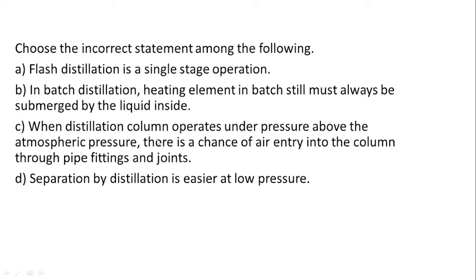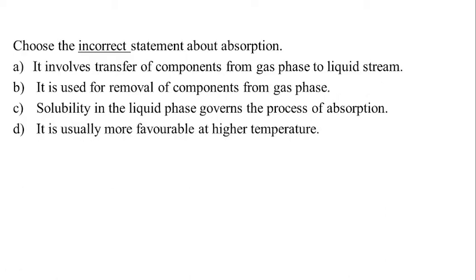It's like this. In many cases, it's a case of pure absorption. For example, if you're talking about carbon dioxide in water at a normal temperature of around, say, 32 degrees centigrade, if you increase the partial pressure of carbon dioxide, more and more carbon dioxide will get into the solution. In this case also, what you find in your liquid phase is that the carbon dioxide dissolves, immediately forms carbonic acid, and the ions dissociate.